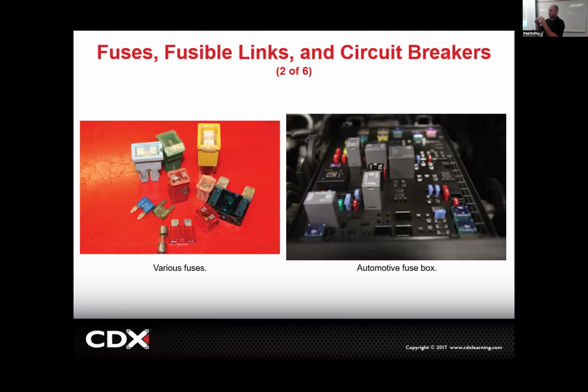It might not blow the fuse today, it might blow the fuse next week, and then poof, your fuse is blown. So if you find that the fuse is blown, there's nothing really wrong with pulling the fuse out and putting a new fuse in. If it fixes it, great. But if you put a new fuse in and it blows instantly, you can keep doing that over and over until you've burned up all your fuses and now you have no more fuses. It needs to be diagnosed, okay?